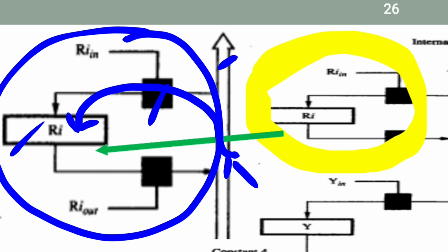This is inputting data to a register through the Rin control signal. If the content of a register has to be taken out, then the Rout control signal is given to that register. Then from that register, the data is put onto the processor internal bus. From there it is copied to any other register. This is how, through two control signals, Ri in and Ri out, any general purpose register can be used for storing data into it or taking data out from it.